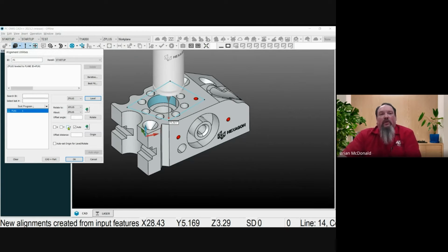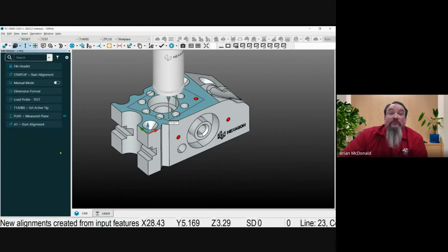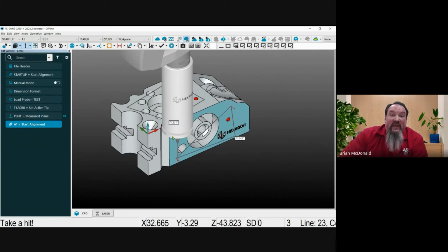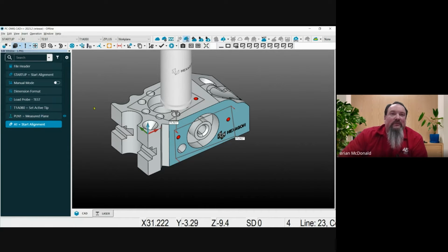If you're doing portable, progressive alignments are a must. If you don't do it using portable, it will flip the CAD model, it will flip the parts, vectors will be wrong, measurements are bad, and you spend a lot of time trying to figure out why. So as we build these, that's what we should be doing. PC-DMIS does it by default if you're using that quick align button.